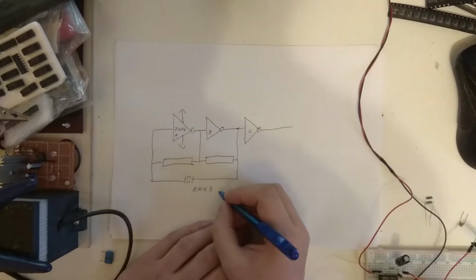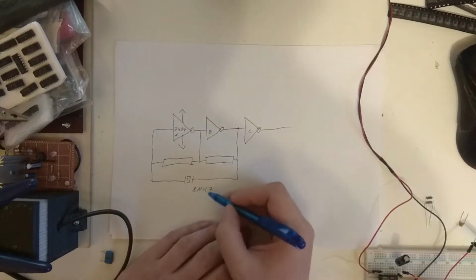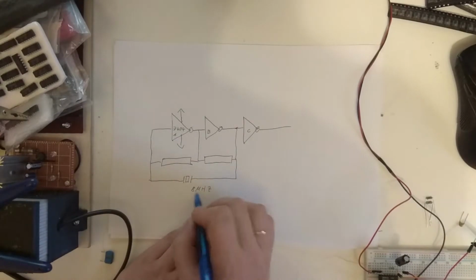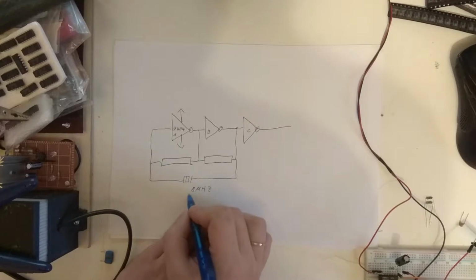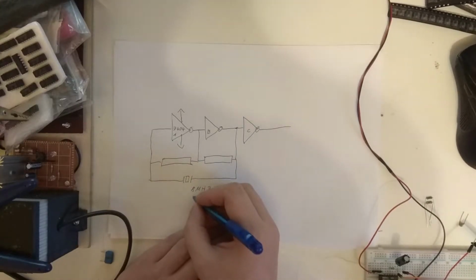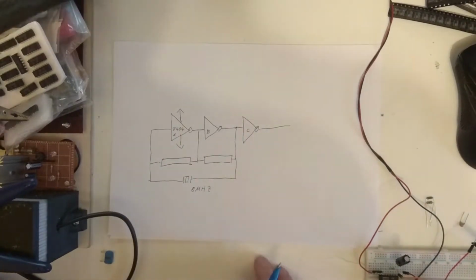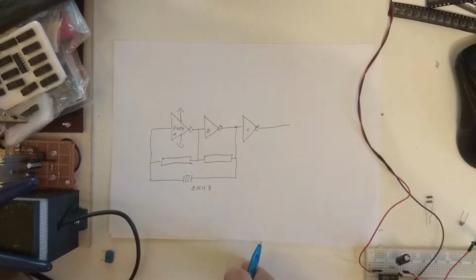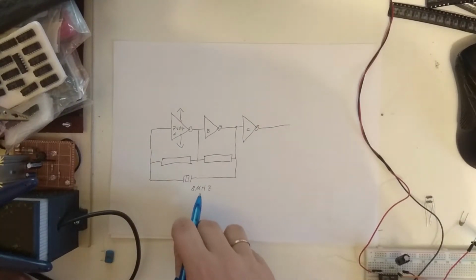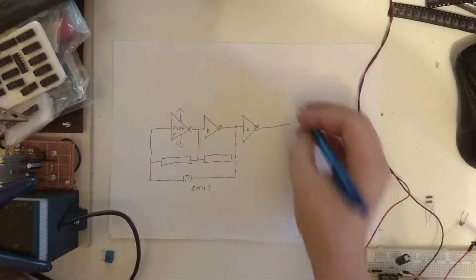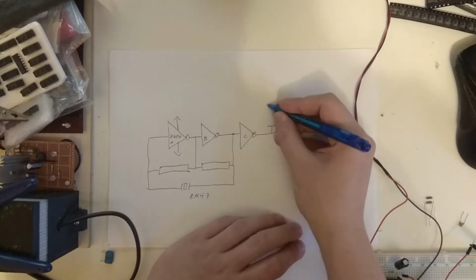But I want to actually change that later on. At least I want to be able to change it, because 8 megahertz makes for a problematic serial clock. So something like I think 7.12 something would be better, or half of that. But I don't have that crystal at the moment, so I'm going to put an 8 megahertz in the socket. And we derive our actual clock frequency from here.